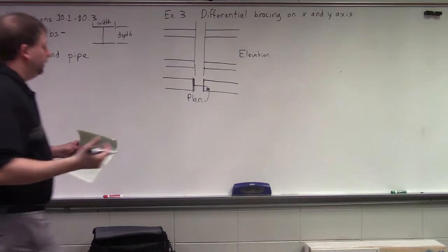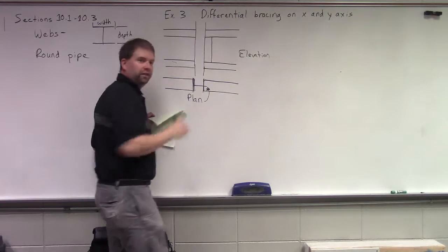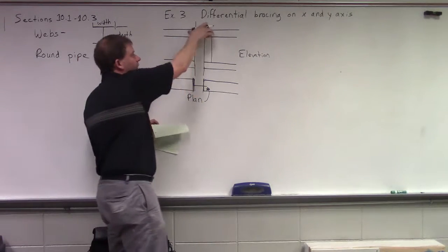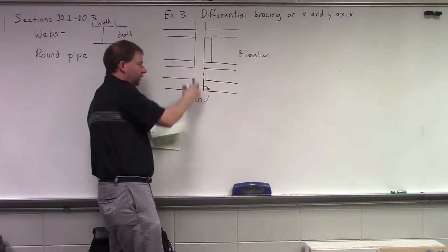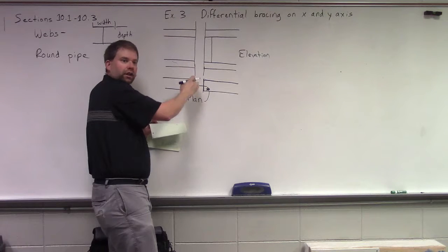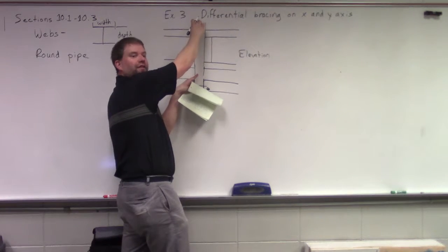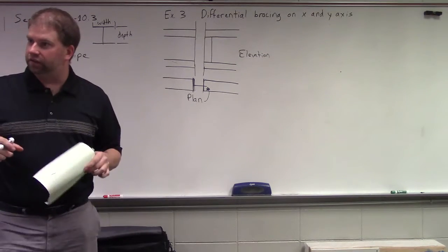As we're looking along this axis, we're going to have a brace length of that length. This is going to act as bracing along this axis. Does it act as bracing along this axis? No, it does not brace this thing at all. So then we need to know what that distance is. That's what that unbraced length will be. Does that difference make sense to everybody?